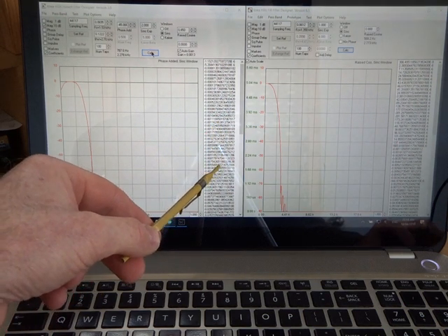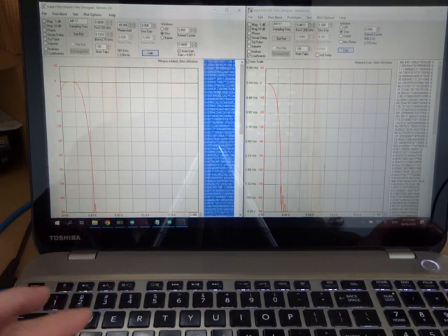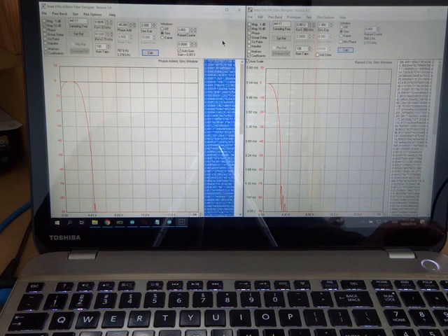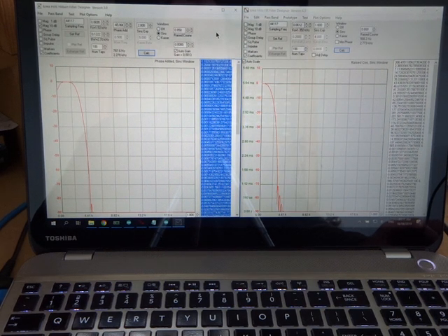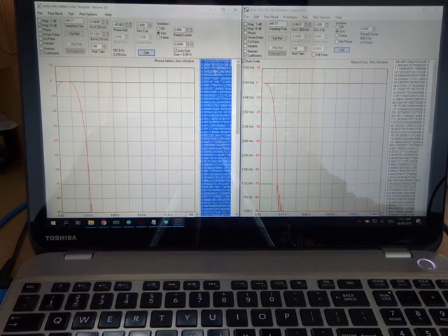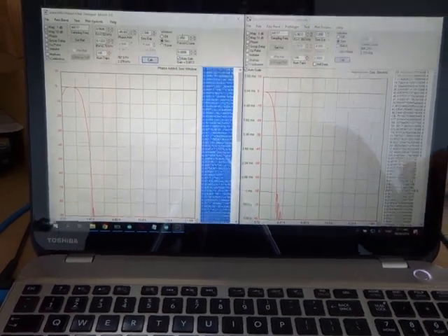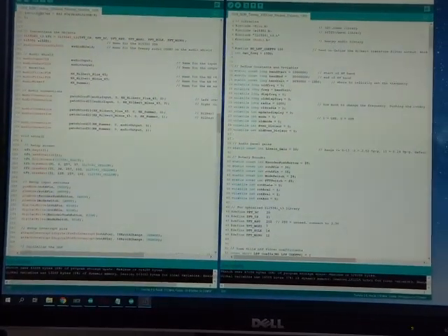Right, so over here on both of these, I've clicked the coefficients, and you can see the coefficients have been generated once I push calculate. Then it's just a matter of control copy to copy all those, and we can then move those and prepare them for inputting into the program. Like I say, the software is free, certainly easy to use, and a good way of generating the coefficients that then get fed into the sketch, which ultimately gets loaded into the Teensy to drive the DSP.